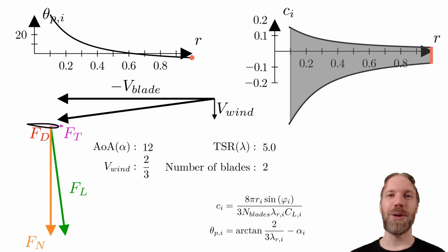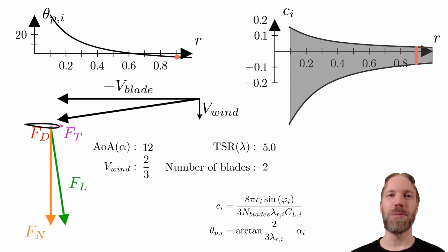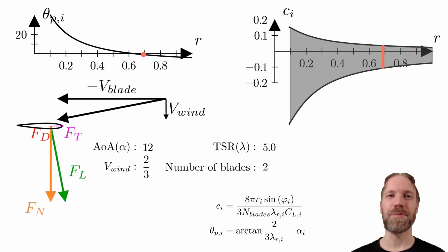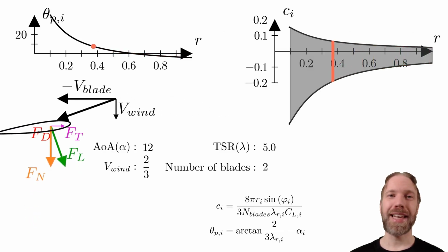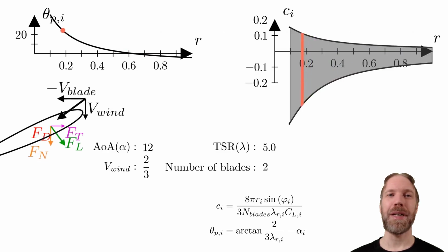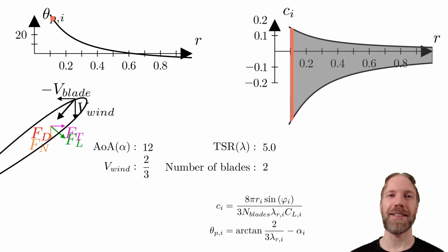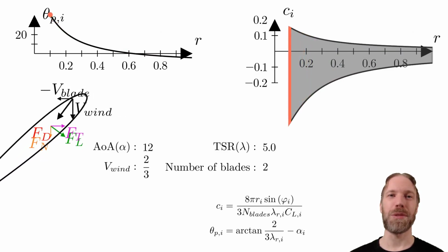This time, note that the tangential force is almost constant when the radius changes, while the normal force varies linearly with the radius. This can be expected since we assume an even drop in pressure over the entire disk. We also assume even power absorption.